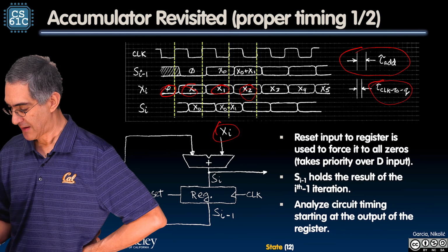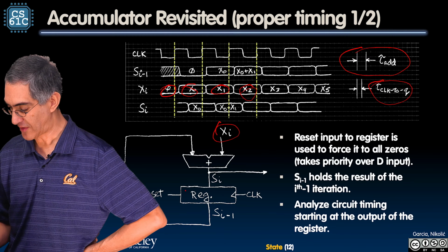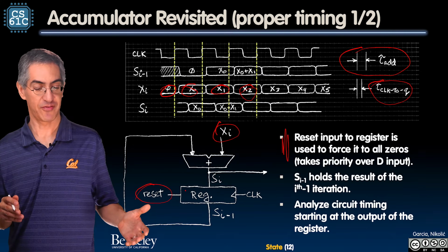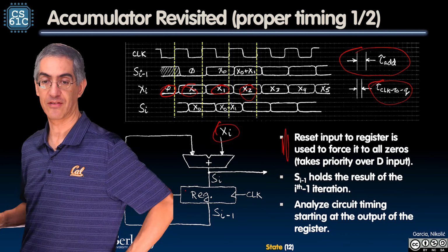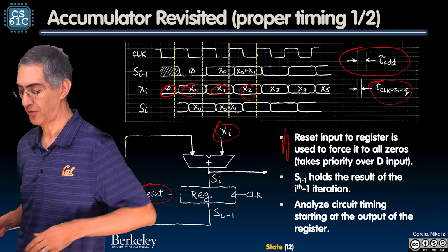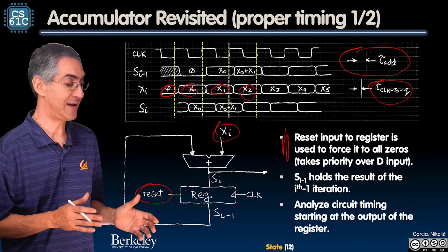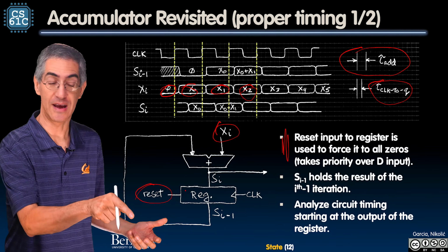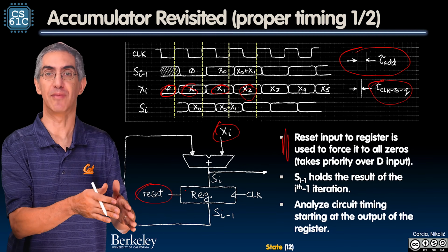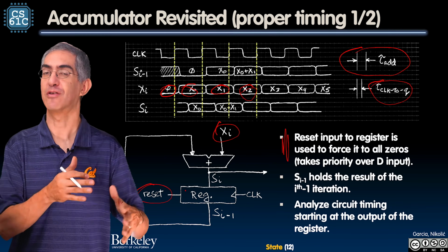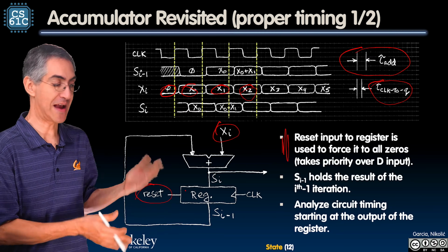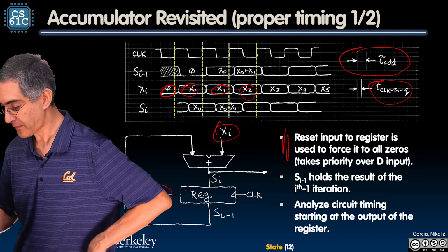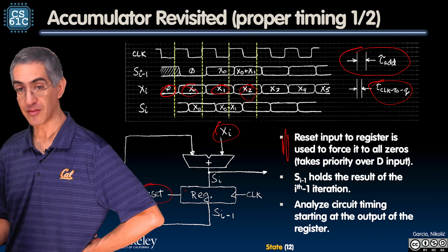Okay. Here's the hard part. This register has a reset button. The most important thing on this slide, I think, is the reset. If the register gets clocked, so a rising edge arrives, and there's an input D, but the reset line is also asserted or high, I'm going to ignore my D and reset myself. So the idea is the reset takes priority over the D. I can't care what the D is, for my job is to reset myself. So that's really important.